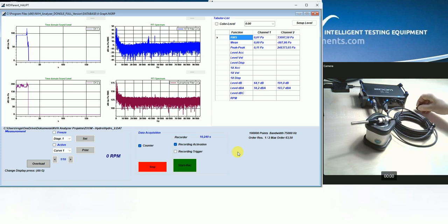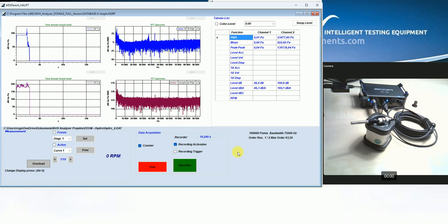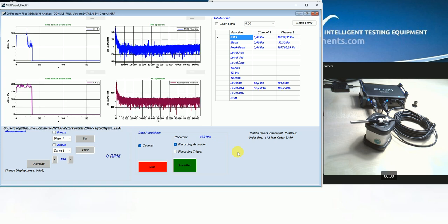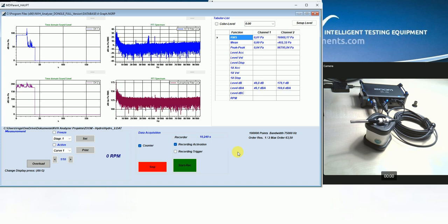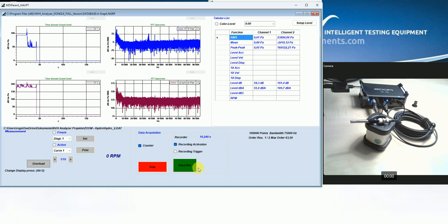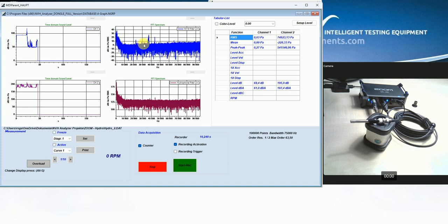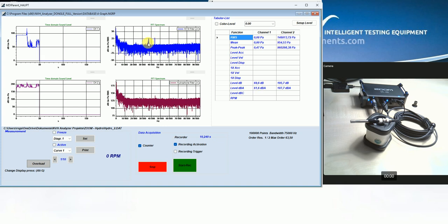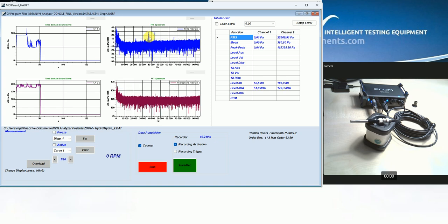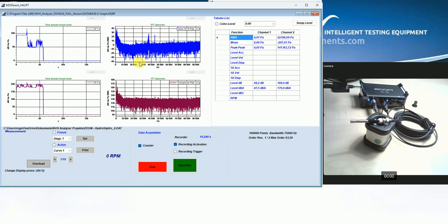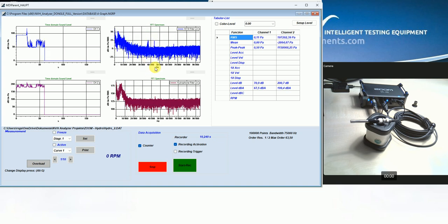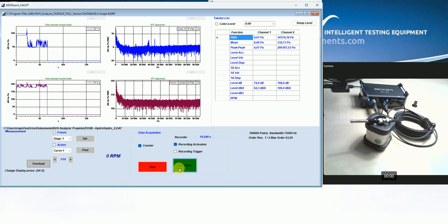And now we see here our environmental noise. Of course, it's possible to change here the setting, for example, to averaged FFTs, so that we can see the ultrasound here in this case at about 38 kilohertz from the microphone. So this ultrasound is generated by the monitor or mini PC. So now I stop this measurement.